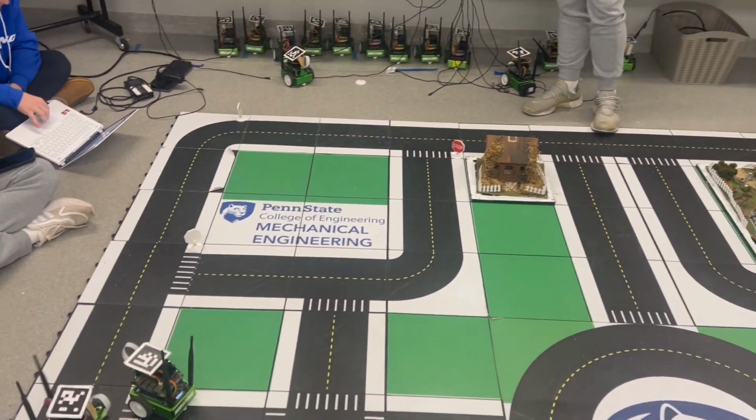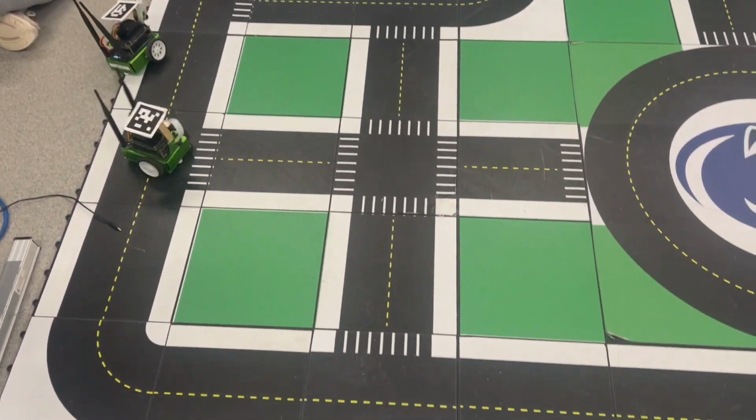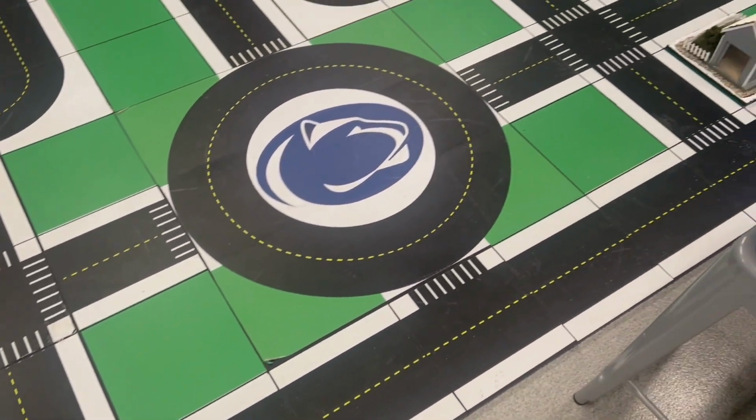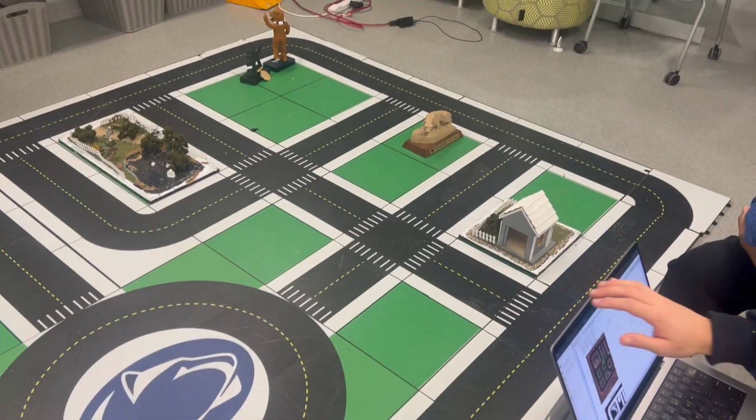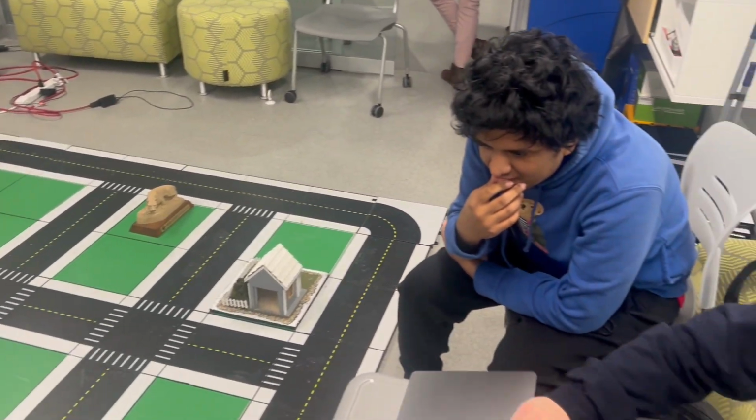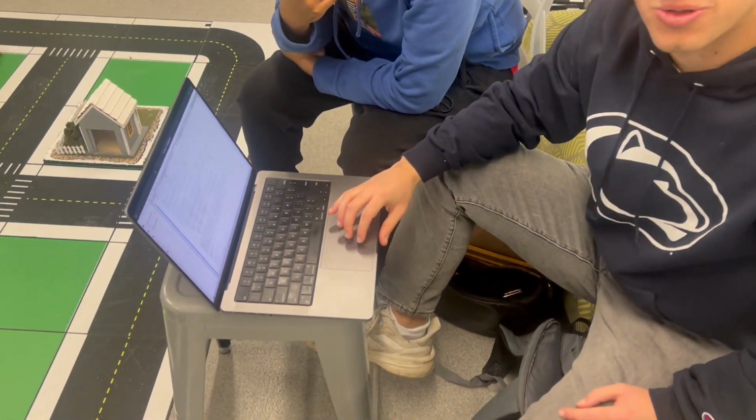Finally, our team used all of this information, including communicating with the CameraBot and the AprilTag location finding, to plot a path. So we were given a map based on where we were on the board, whether we were towards the window or towards the door, we were towards the window. And then we used this map along with a number of different nodes and a number of different algorithms to figure out the shortest path between our starting point and the end point. Using this, we were able to plot a path which showed where our JetBot needed to turn and how far it needed to go.